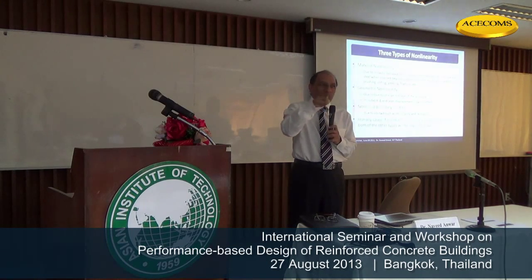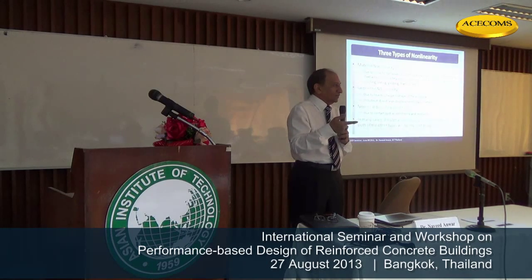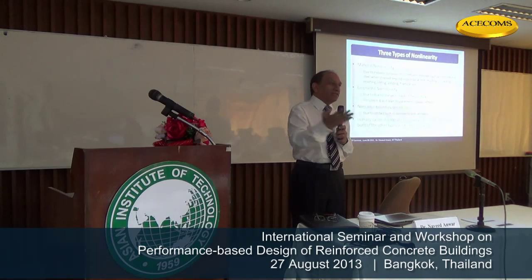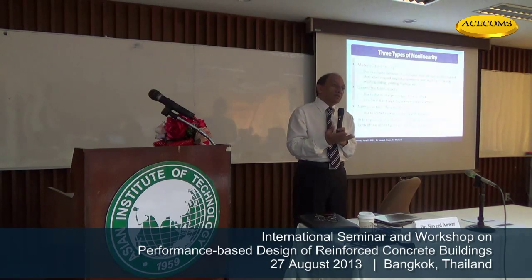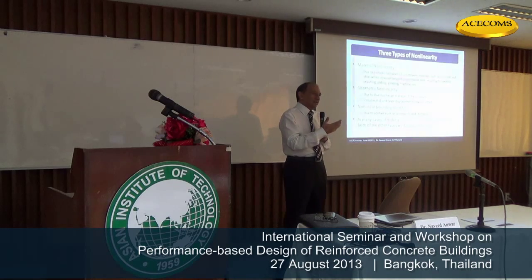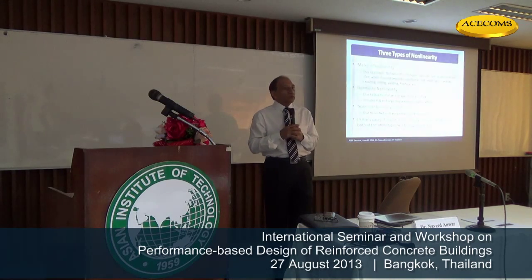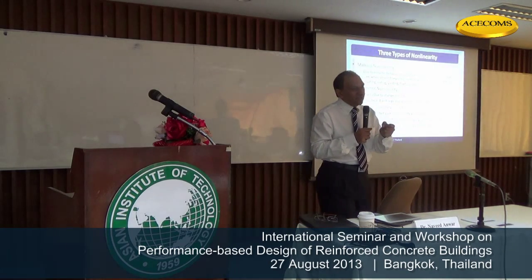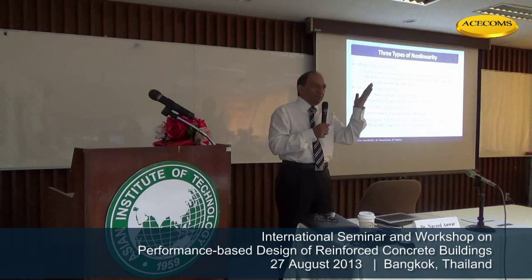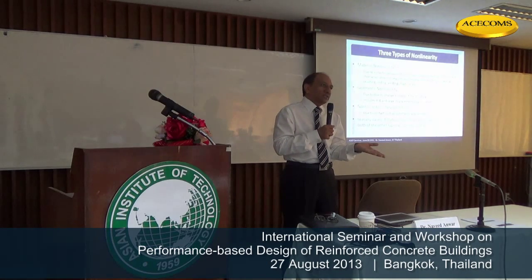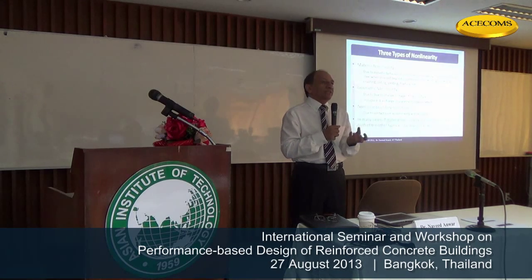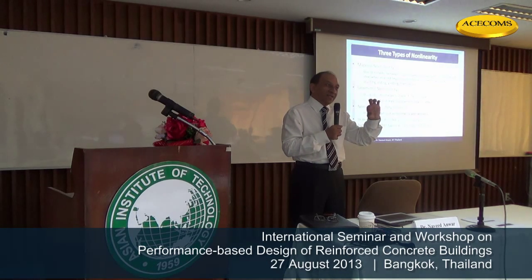There is no such thing under the column with 4 lines and a horizontal line, right? There is a footing. Below that there is soil, many layers of soil and water and so many things, which are all just as nonlinear as our materials, even more so. So that nonlinearity of the boundary needs to be included. Not only that, if you have a lot of overturning, the foundation can lift off. That means the contact between the footing and the structure can be broken. So that means no contact.